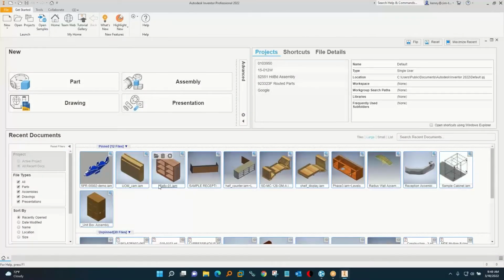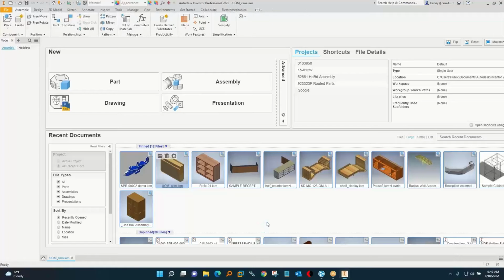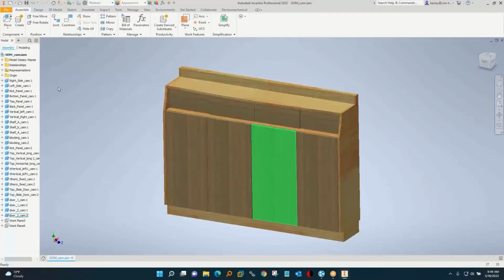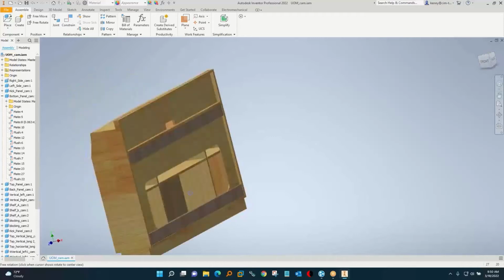So if we grab an assembly from Inventor, again, you've got your part names from Inventor. And as you pick these, you have your material names right here. SW3 is the material name. And we can use the grain rotation from Inventor, or we could emboss a symbol on there that tells the parts what direction to rotate.